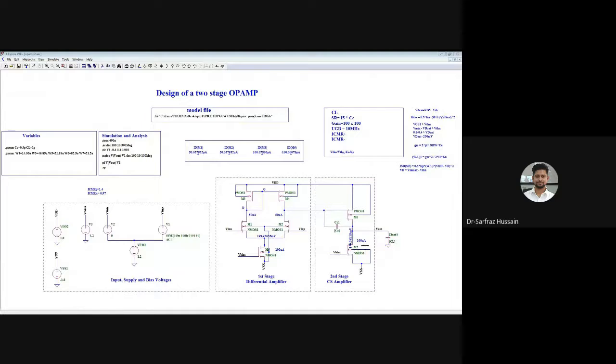If there is a different current value over here, since the bias point is same, and the output swing, let us say if I am keeping it at 170 or 200, I already know the VDsat value. From that VDsat value and our current specification, I can find out the value of the transistor M7. And the M6 value we can find through the matching property, the current in this one and the current in this one. So I6 upon I4 is equal to the dimension of M6 upon M4. This will give us the value of this transistor.